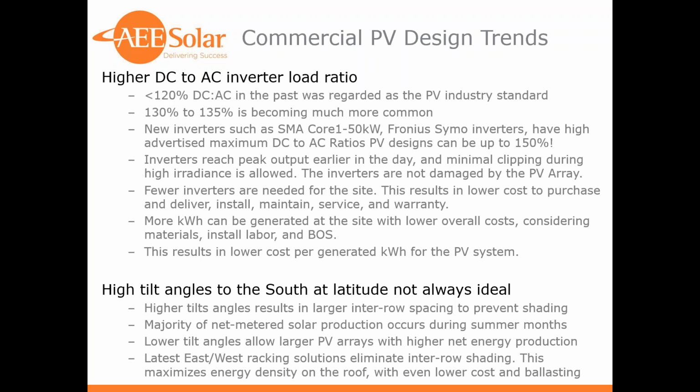If clipping does result, typically it's only a couple hours during the year, and you can calculate those clipping results using some of the more advanced planning tools. HelioScope is one of those from Folsom Labs, if you have access to that, or PVsyst could calculate the loss. And typically, if you can keep that reasonable and consider how many inverters you may save on a larger installation, it's much better to do that.